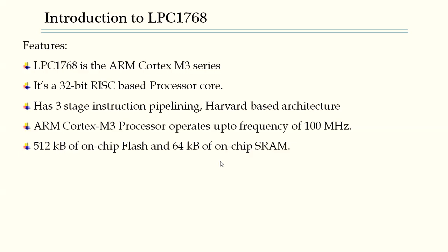The devices containing more than 32 KB SRAM have an additional 16 KB SRAM block, and each is situated in a separate slave port of the advanced high performance bus. The architecture here allows the CPU and the DMA to be accessed separately such that few or no delays occur in the bus mastering.